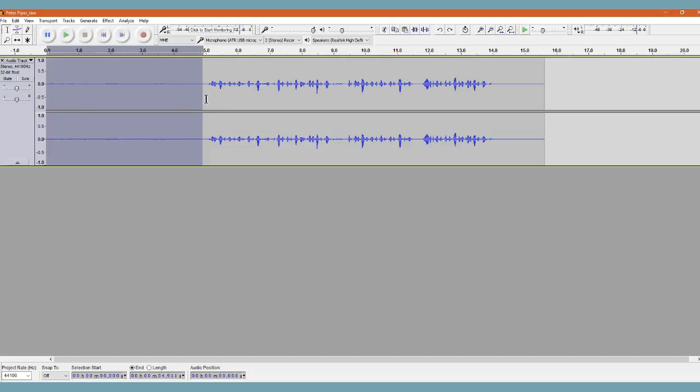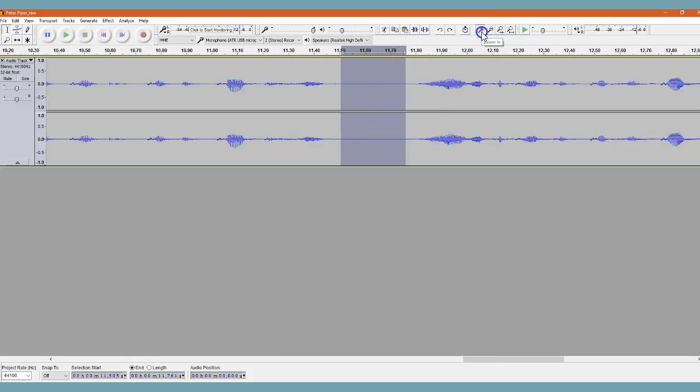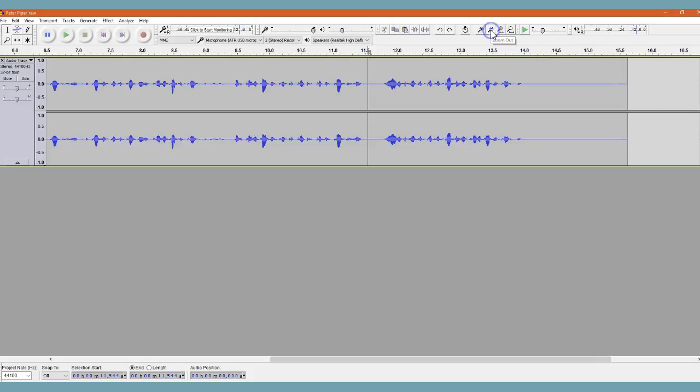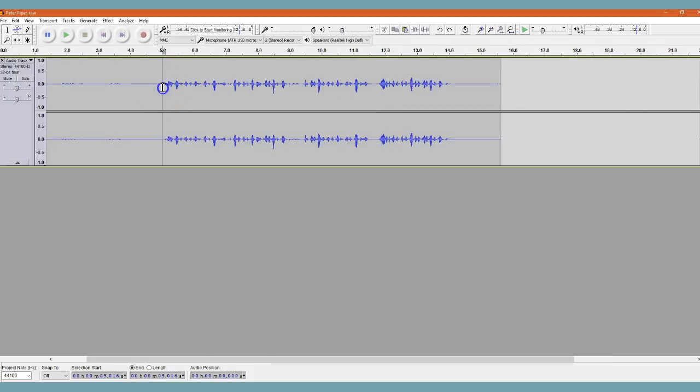If you don't have a buffer at the beginning of your track or at the end of your recording, look for a section in between wave peaks in the recording and use that for your noise reduction sample. You can zoom in on a section of the track and select a sample to use. Now, since I have a buffer, I'm going to highlight that portion by clicking and dragging to select with my mouse.